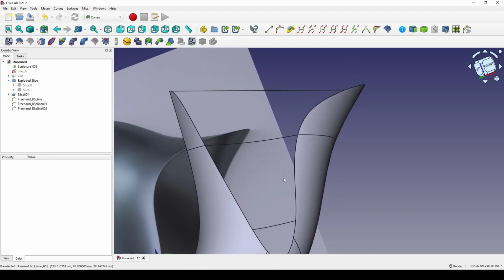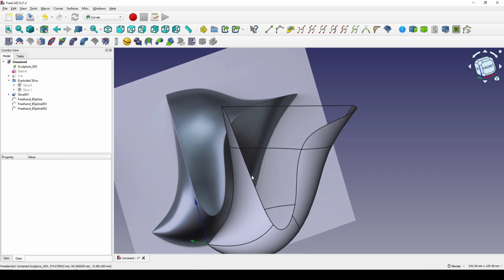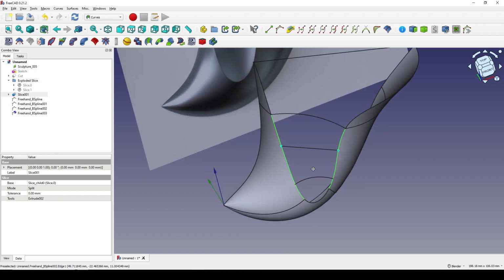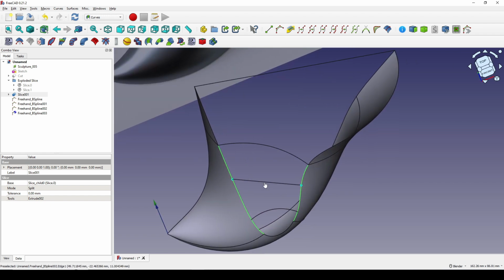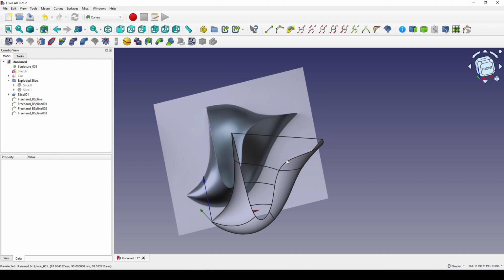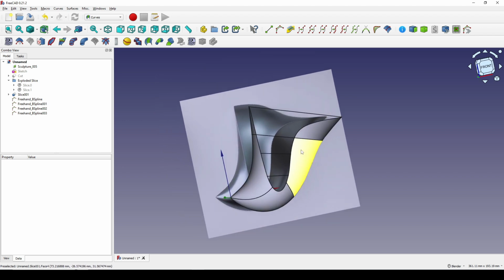Maybe I should create another freehand B-spline up here. I Control select this line and this line, freehand B-spline. Select this line, hit I, move it, hit Y, move it in a little bit. Alright. Now you can save it.